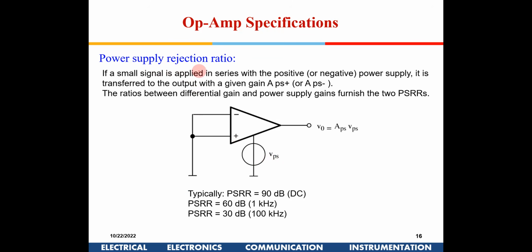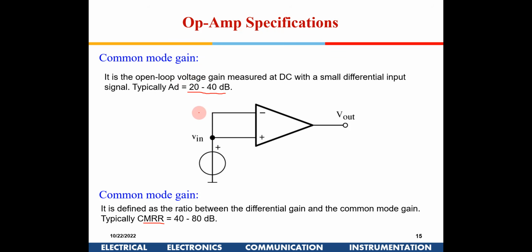There are a lot of other criteria also. You can keep cascoding the current source one above the other to increase the resistance and make it close to ideal. But if you do that, you will consume more power and more headroom. So it is all a mix and match.